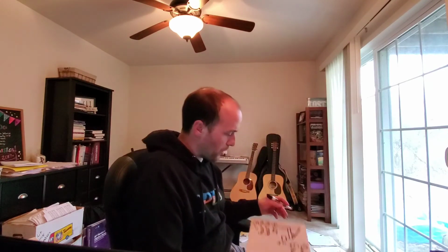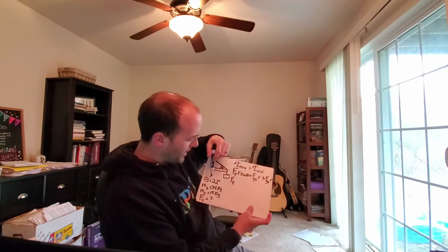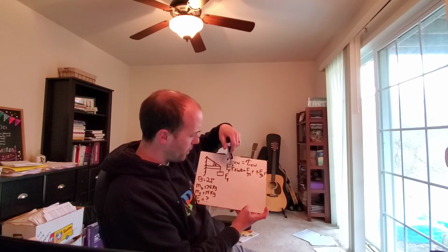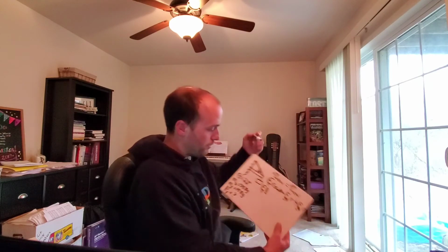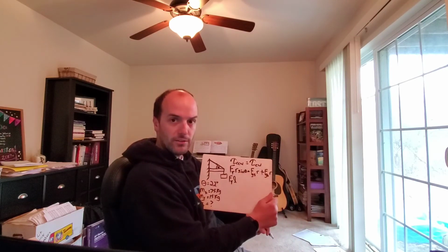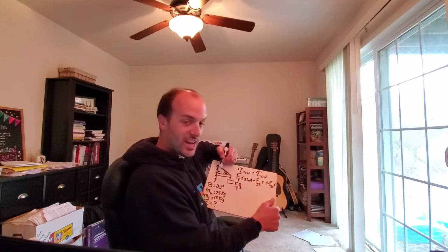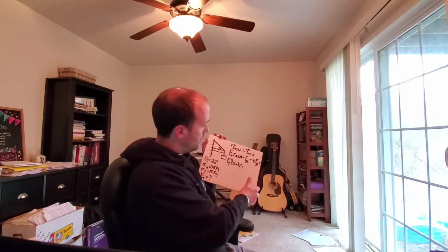Force of tension, that's our unknown, times the moment arm. Interesting. I didn't give a length. So how can I calculate or write down a moment arm if I didn't give a length? For now, I'll just substitute an L for the length of the beam for that moment arm, because the pivot point's here, the cable acts on the end, so that's the entire length of the beam. Times the sine of 22 degrees equals,